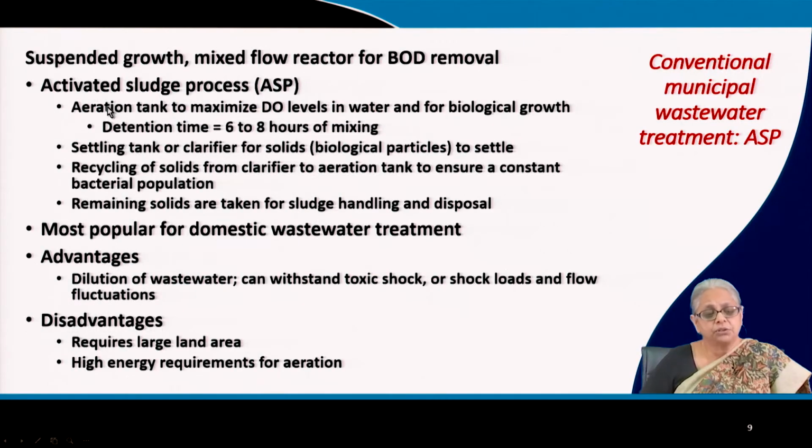So I've already mentioned that this aeration tank maximizes the DO levels. It can have a detention time of anywhere from 3 hours to 8 to 10 hours of mixing. And remember, the more time you provide, the greater the efficiency, but that also increases the cost of treatment. So it's a fine balance between the economy of the process and the efficiency of the process. These two factors will determine what the practical detention time is.